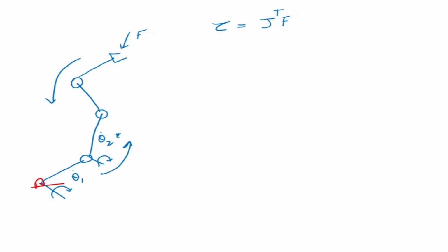What makes this very important in terms of motor control is the way we talked about motor control; we'll come to control a little bit later after a few more lectures. But we have a motor, we have a gear, and we have an encoder. This is what we call independent joint control, and this controller is controlling the joint independent of the other joints. That means each joint is independently controlled.